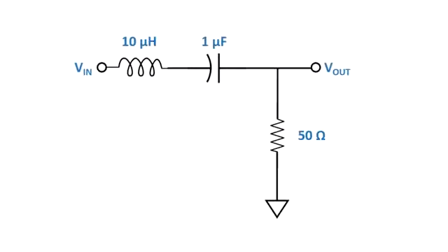Hi, I'm Johnny Hancock, Product Manager for Keysight's Infinivision X-Series oscilloscopes. In this lesson, we are going to characterize the gain and phase of a bandpass filter that consists of a series inductor, capacitor, and resistor, as you can see on your screen now.